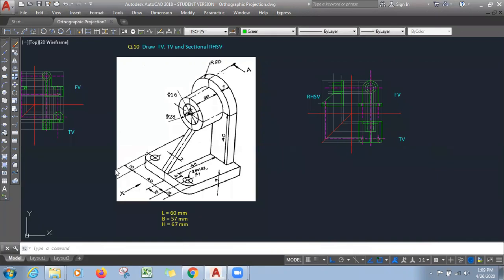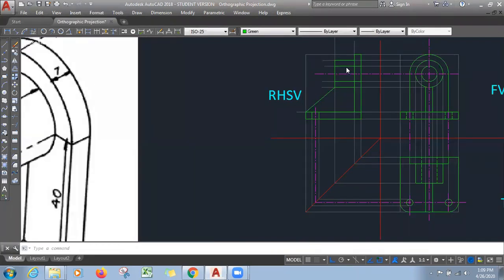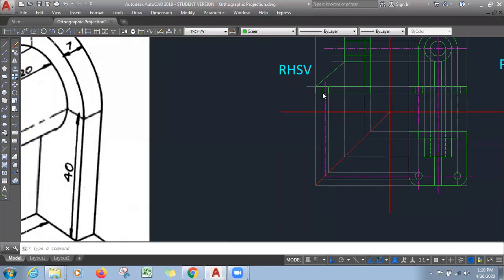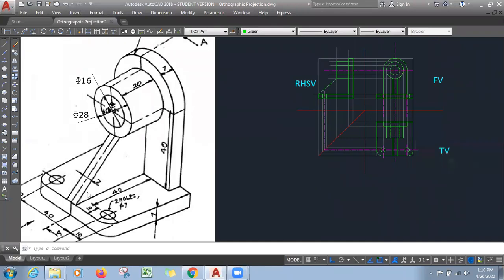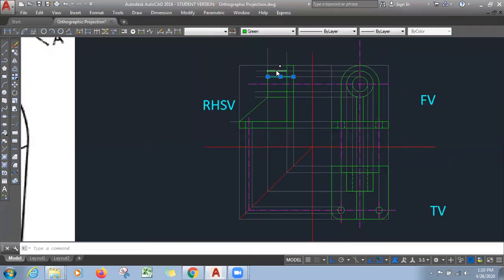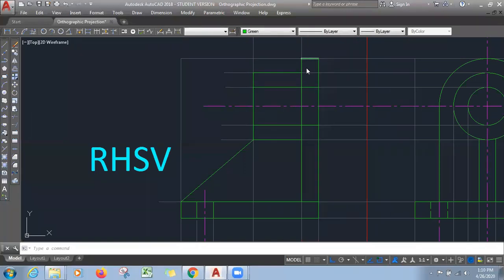Now let us have a look at the sectional view. Actually these lines are dotted lines, and these two are also dotted lines. See, for sectional view, what happens? At this point we start cutting. For example, suppose top to bottom cutting is being done, at this point we are starting cutting, so from here where will it go? First slot of cutting will start here and it will end at the start of the hole. Hole is where? At this level. So cutting will start here and end at the start of the hole. Hole will be completely exposed.